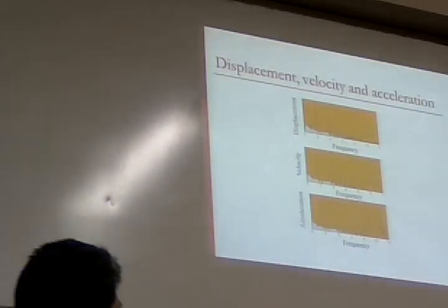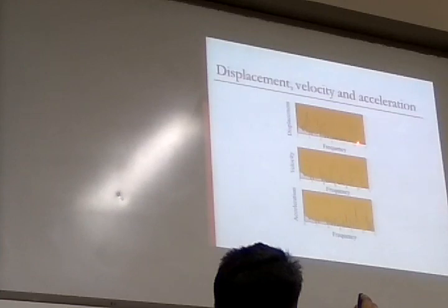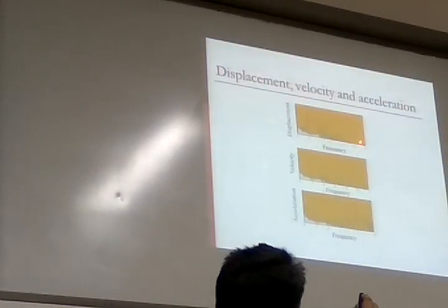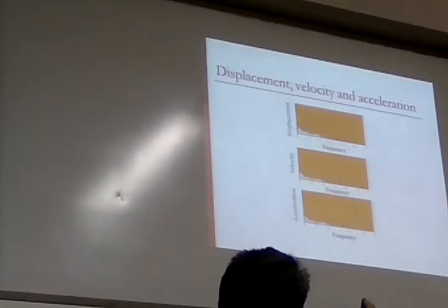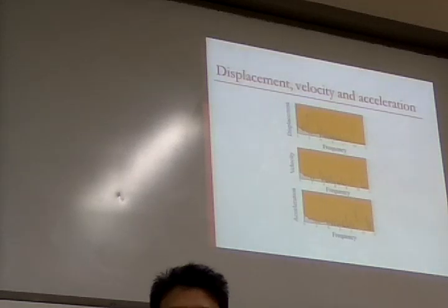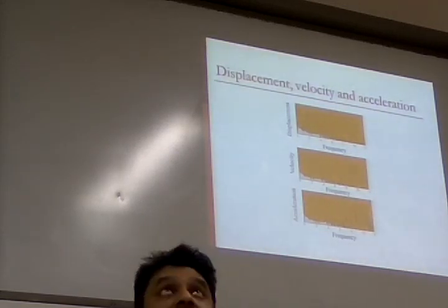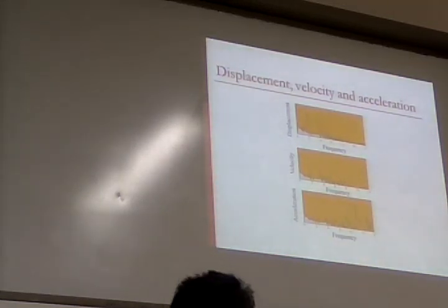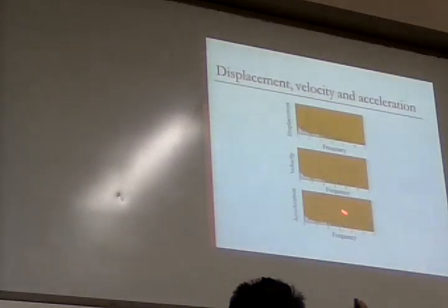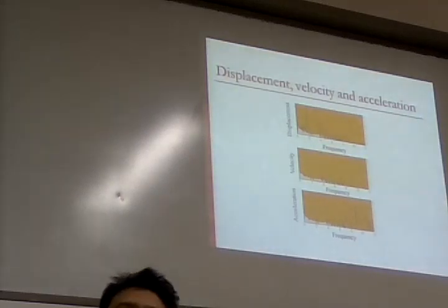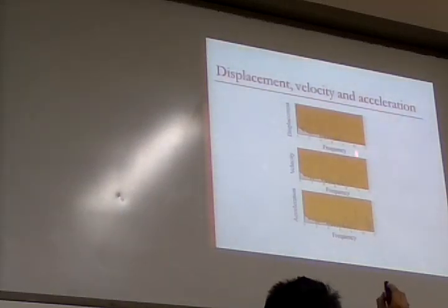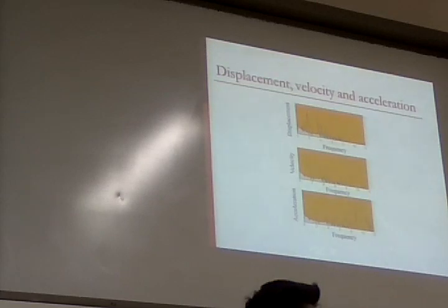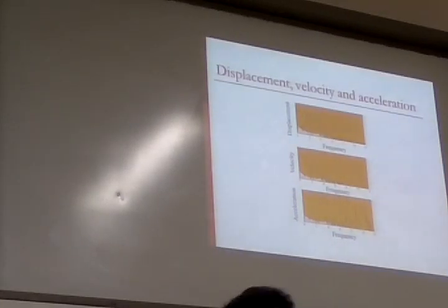Whether this is 0 or it has reached a threshold, measuring here is difficult. The same signal in acceleration is easy to measure because it is amplified multiple times at the higher frequency. In this case study, I am not interested in the low frequency signal at all. I am only interested in the high frequency signal, so frequencies of 10 Hz, 12 Hz.